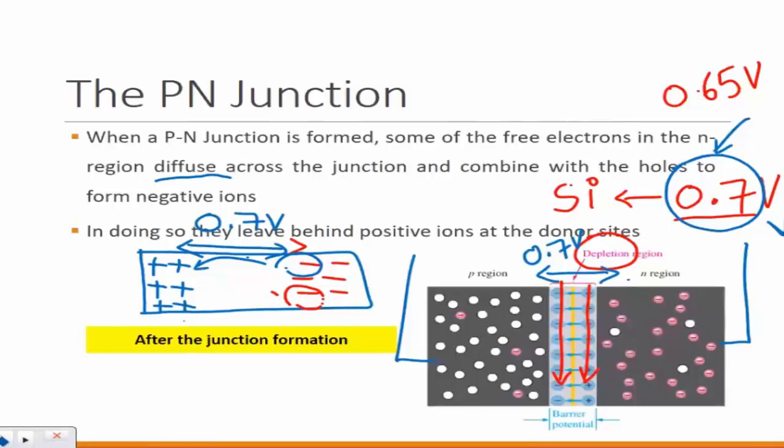That's what solar cells are. You will get that 0.7 or 0.3 volts, depending on the solar cell or the light energy, but all those are placed either in series or in parallel to accumulate the voltage or current. Remember, if you put them in series, more voltage, right? Put them in parallel, more current. That's given when you're dealing with silicon.